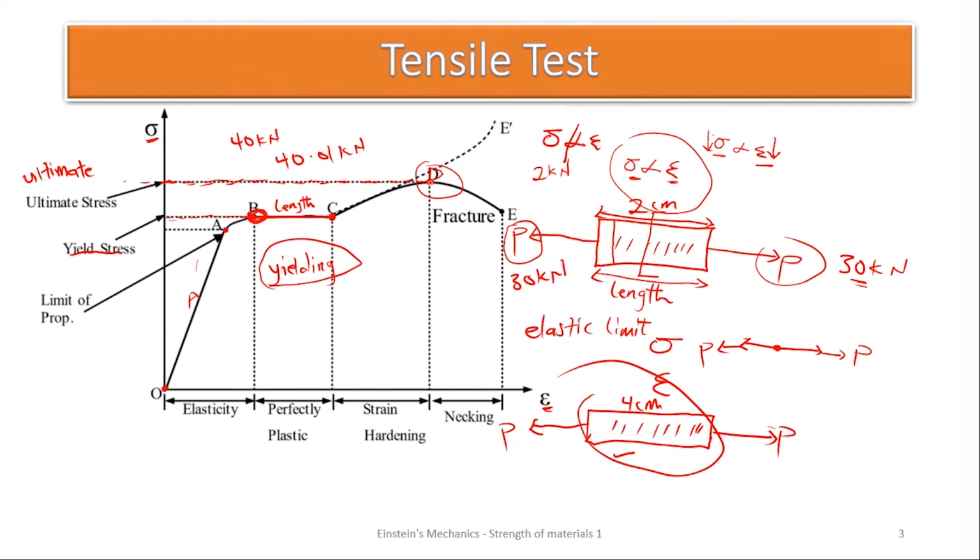What is going to happen? Let's see. The material now is going to break. Look at the graph. You can see that it is now decreasing. So the size, that's what we call the necking. It is going to reduce. So look at the size.